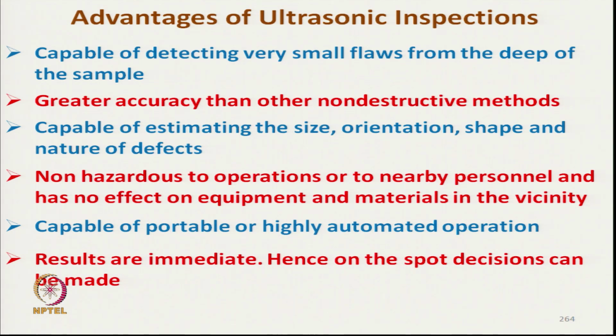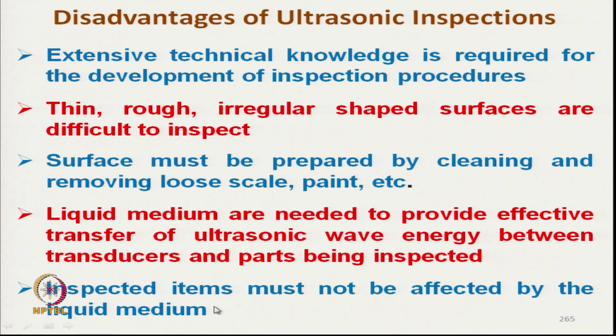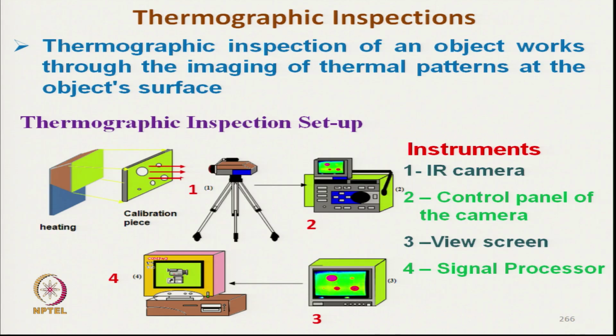So, we can take that instrument to the actual site and we get the result immediately. However, extensive technical knowledge is required; those are the disadvantages. A thin, rough surface is difficult to measure. It should be a clean surface, a liquid medium is required, and the liquid medium should not react with the composite surface.